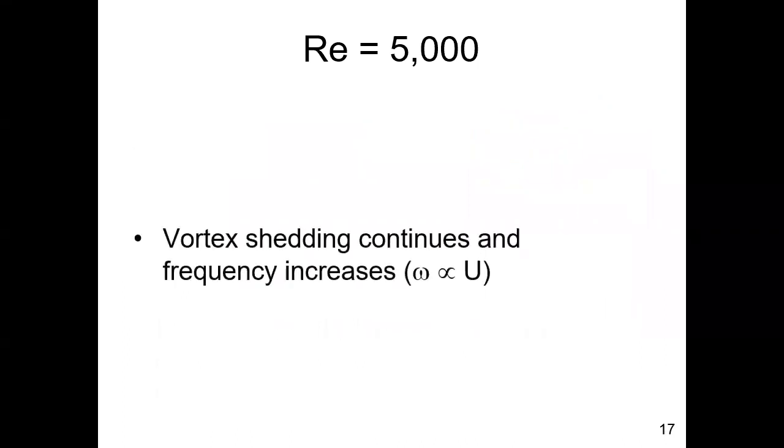So the vortex shedding continues, and in fact, people have developed meters. The frequency of shedding is proportional to the velocity. So you can actually estimate the free stream velocity just from measuring that frequency. For example, you could have, on a ship or an airplane, just a wire that's vibrating, and by measuring the frequency of that vibrating wire, you can get the velocity of that object. Or you can use a pitot tube, like we discussed before, and use pressure to recognize that from converting V squared over 2g equals P over gamma, you can measure velocity.